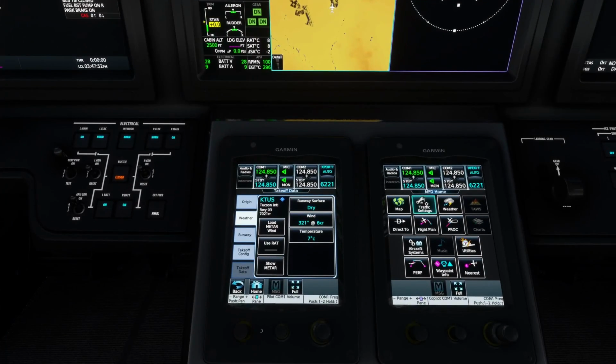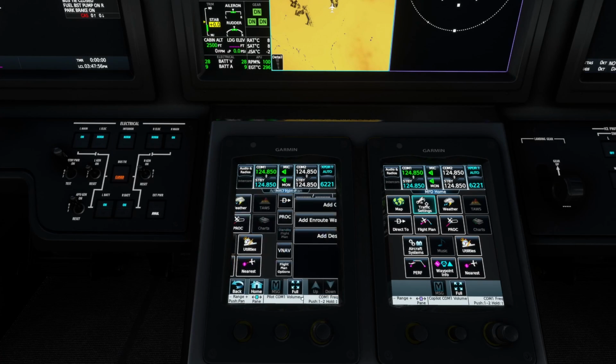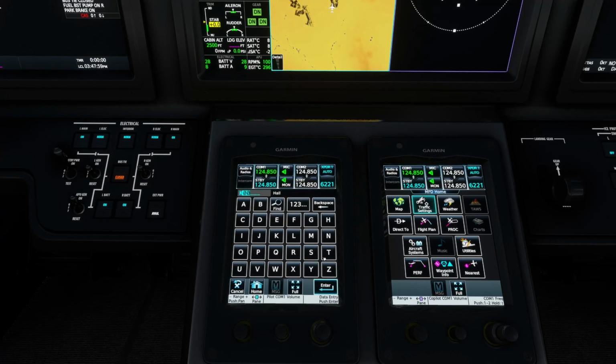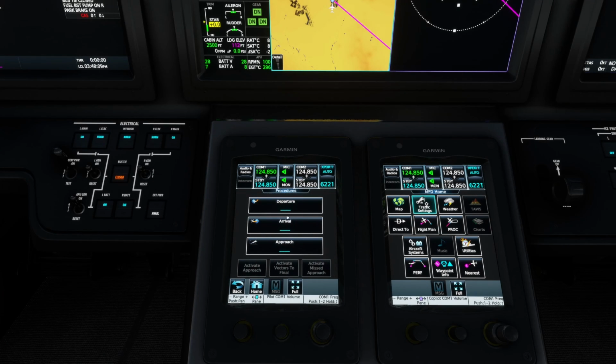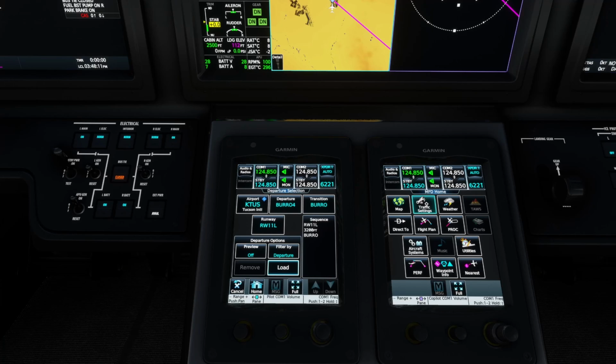It doesn't take us long to set up the flight plan, so we're going to get started on it right away here. We're going to move to home, go to the flight plan, set our origin as Kilo Tango Uniform Sierra for Tucson International Airport. We're going to set our destination as Kilo Lima Alpha X-Ray. Moving on over to the procedures, we're going to be departing using the...